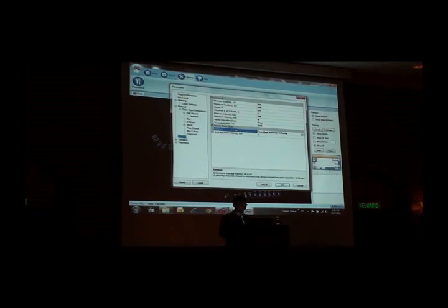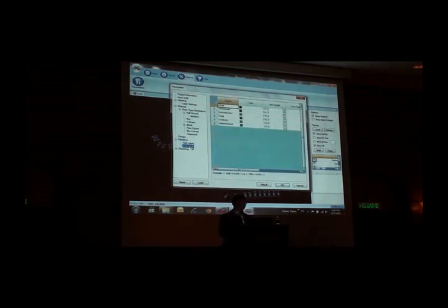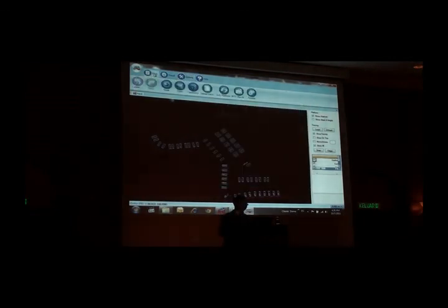And then for the drainfall time, we can choose the method. The method is a constant average velocity, that means 1 meter per second. Or we can choose Manning's equation, to calculate using the Manning equation. And then this is our long section setting, the horizontal and vertical skew. And the rest is the coloring, text height, all this simple setting. Okay, so that's all. So come back to the input.